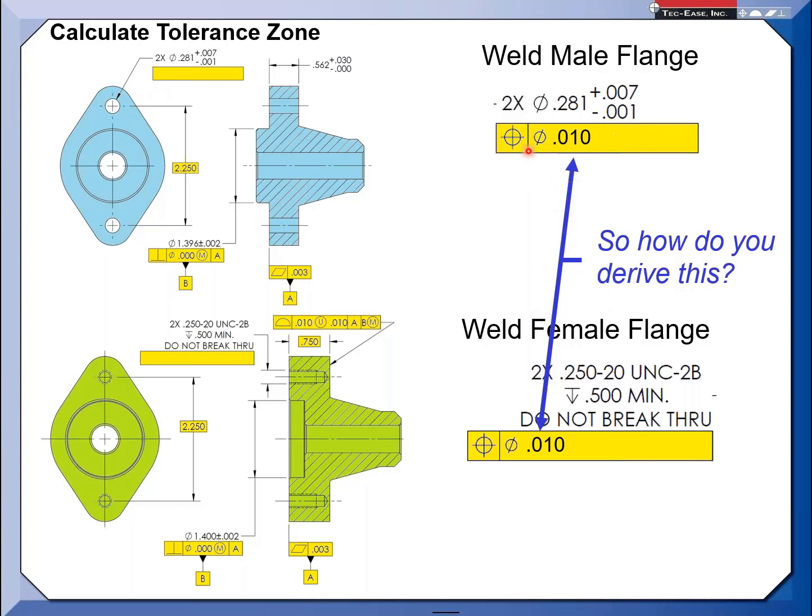allowing assemblability? You're going to find out this number is kind of small, that we could have allowed manufacturing a little bit more because of some of the rules that we have in the standard. Would this work? Yeah, but you took some tolerance off the table for manufacturing if you just jump right to this number. I can't tell you how many times people default back to the plus minus world and just convert drawing block tolerances and start throwing them in the feature control frames. I've seen that. It's not illegal, but you're going to find out you took some tolerance away from manufacturing. If you really make the true assessment of the smallest hole, and how much variation the threaded feature goes with the bolt coming in here. So that's what we're looking for.